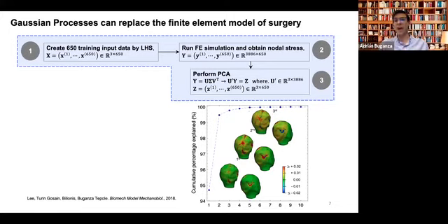And what you see is that the output that you get is the stress response over the entire mesh. And then the number of nodes that have a non-zero stress distribution is about 4,000. So then if you just stop right there, you would have to build a map that goes from this three-dimensional input space to this four-dimensional output space. And that's also not that convenient. But again, there is some structure that we should exploit because we are solving this PDE.